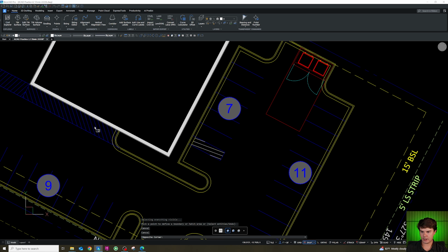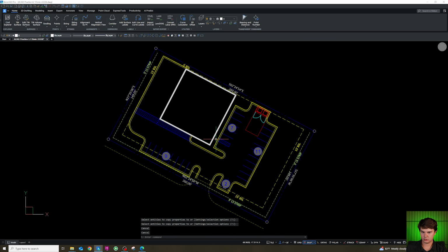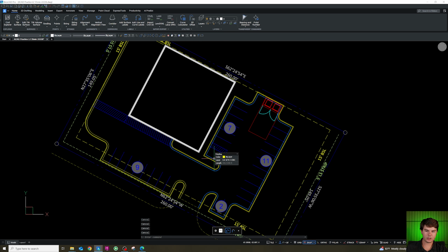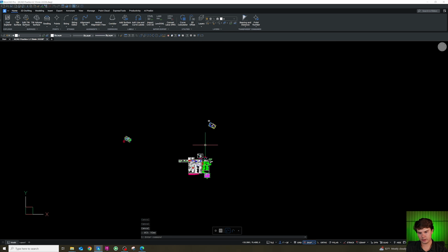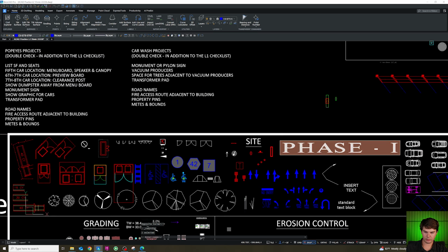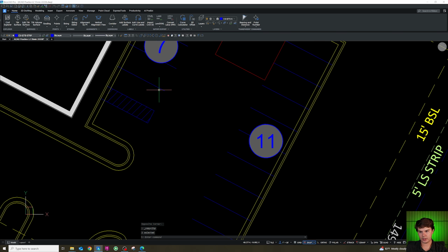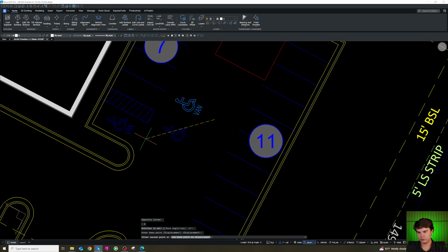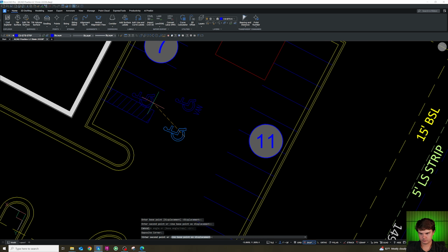That, and then I'm going to match with the MA command, this to this. Okay. So now we're hatched. I'm going to label the handicap spots. Set my UCS to world and copy this, and then set back UCS to site. Hit paste. You can rotate these and hold shift, and it'll rotate ortho. You can move these to their respective spots.